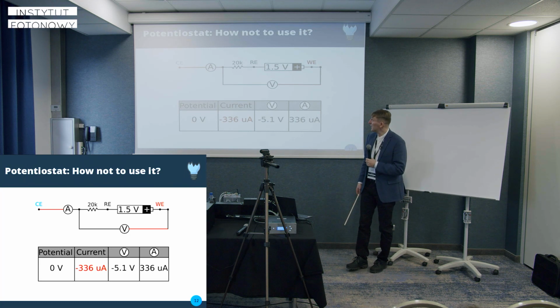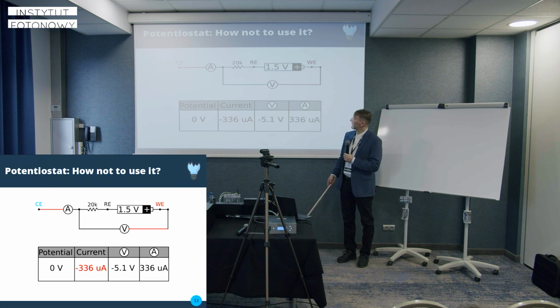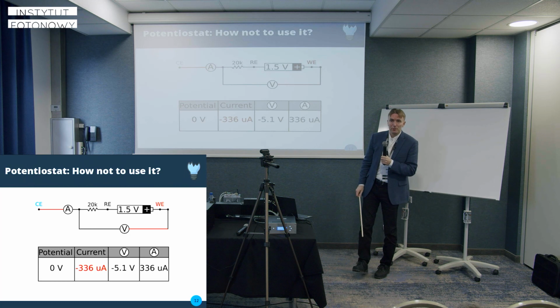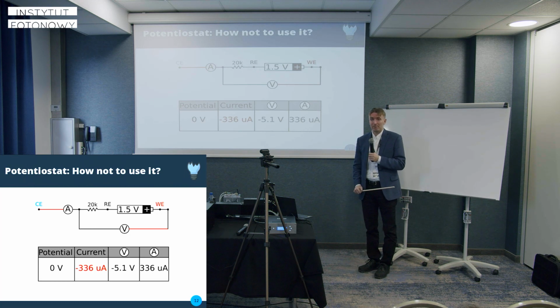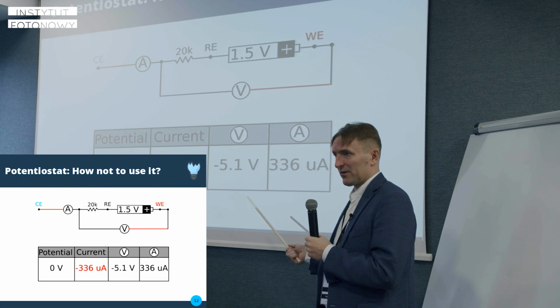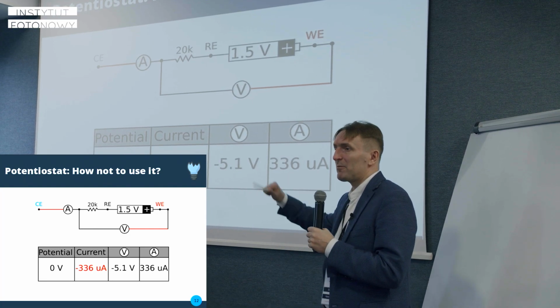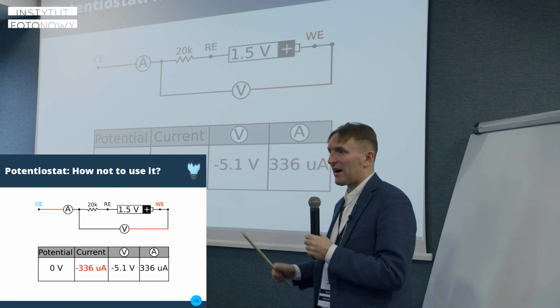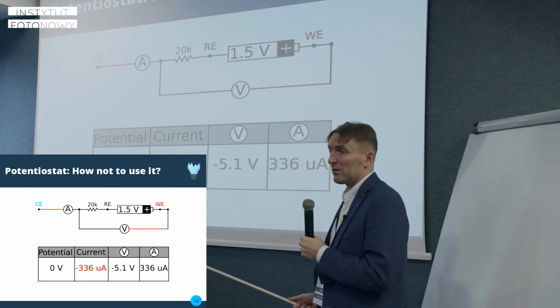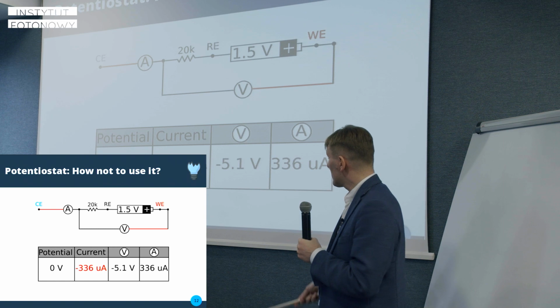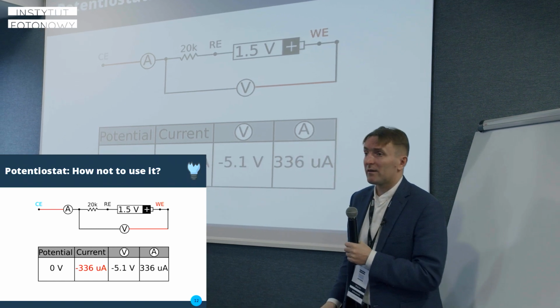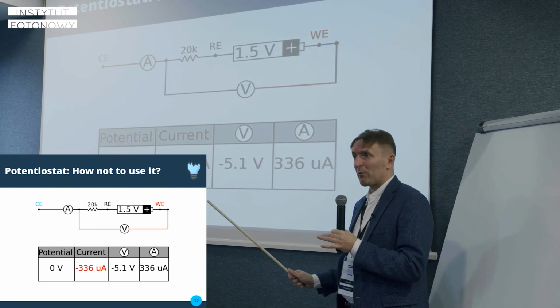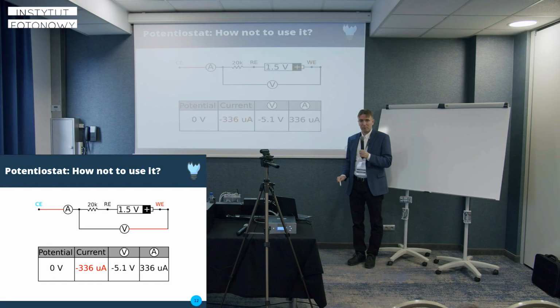So that would mean that if it was 1 ohm and we wanted to lose this 1.5 volts, we would need to produce a current of 1 ampere. Our device cannot do this. It hits another limit because it cannot apply a voltage high enough to the sample to even get close. So this value is completely wrong. It is our misdoing.